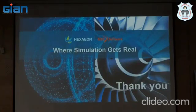Sir, finally, which one is better, subtractive or additive? When the complexity is high, additive manufacturing. When the complexity is simple, subtractive. Additive manufacturing, we say, is not going to replace anything. It will be complementing, because complex design with conventional methods is difficult, so there additive plays a major role. It will be one of the substitutes. It is not going to replace casting or machining, no, because many 3D printed parts are machined for a better surface finish.